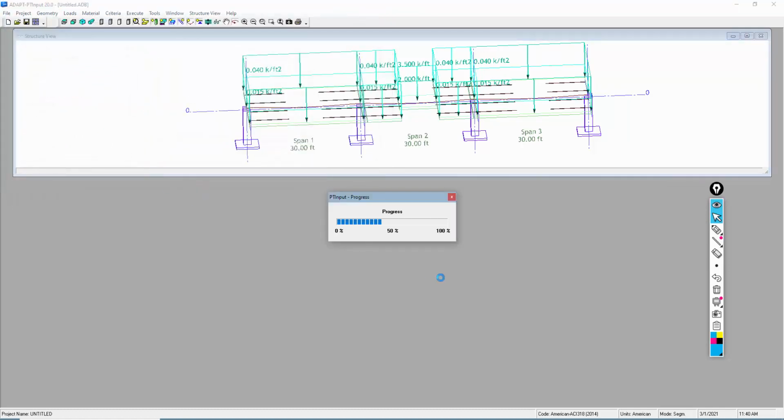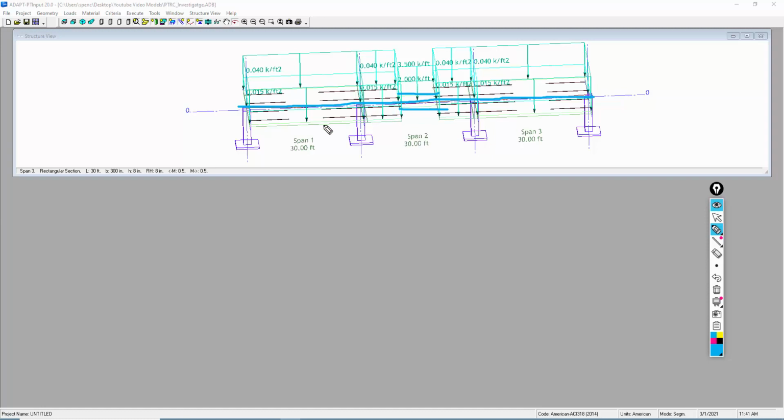All right, and we're going to assume that for this particular slab, this might be a banded run. So all of our cables are kind of along the center line. That may have limited them actually cutting out or cutting further, let's say, into this zone. We need, let's say, 2.5 times the slab thickness or some requirement of distance away from the edges of this band, this existing band. So that's why we have this throat that we're kind of working with here.